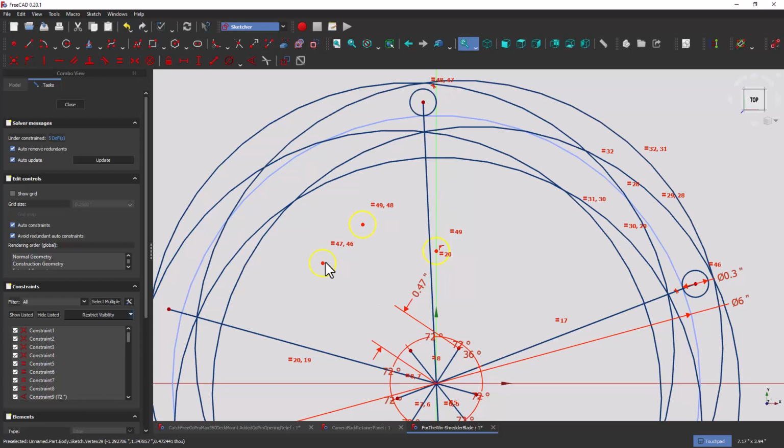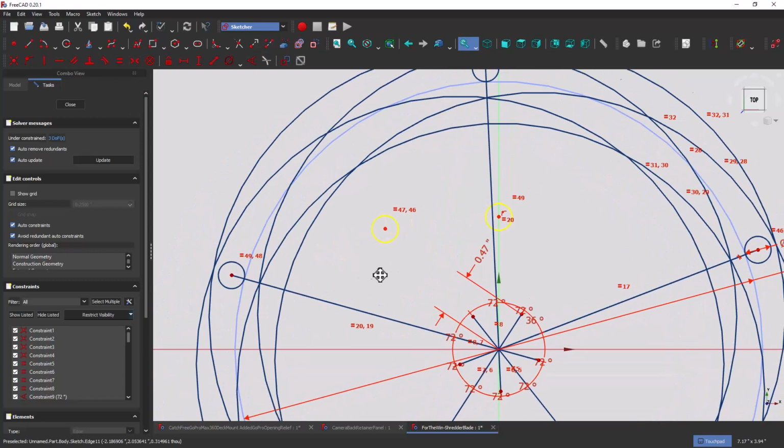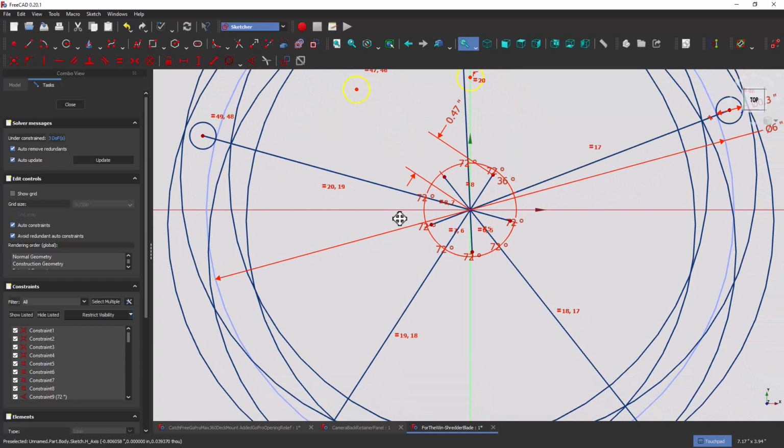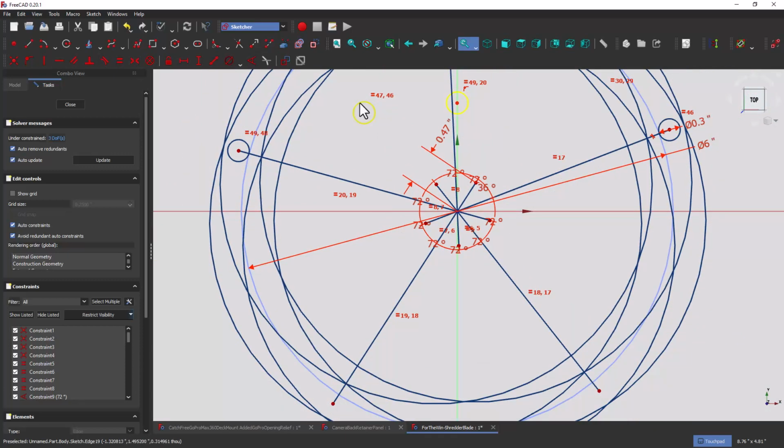Okay, so we'll take one of these, drop it over here, and remember to make them tangent, because it won't close the wire and you're going to get one of those open wire errors. Okay, that looks good. Bring it down. Might have to pull back a little bit here. Drop him on that and make them tangent. Got that, tangent. Get our last one.